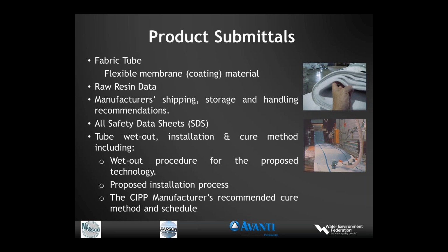Manufacturer shipping, storage, and handling recommendations need to be included. We need to protect these materials while they're being shipped, stored, and handled. Safety data sheets. And then very important, the tube wet out, installation, and cure method in accordance with manufacturer's recommendations. And the last bullet you will see several times because it's a very important step in CIPP installation, and that is the manufacturer's recommended cure schedule. Very important that that is always followed.